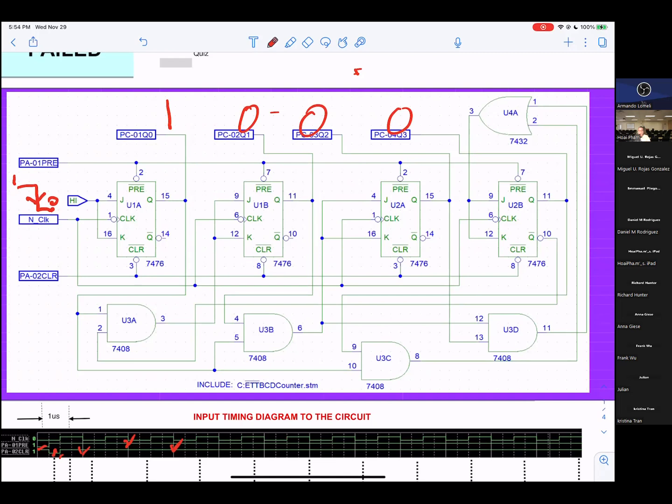That means when it runs into that, apply the clock, you can connect the meter into pin 1 of U1. And you press F10, it goes to the next line. Or you can press F11, it goes inside the clock. Okay? And when you press F10, you can see the clock going to 0. If you press F10 again, it goes to 1. Okay? So that is the way either technician or engineer, we have to learn how to do it.